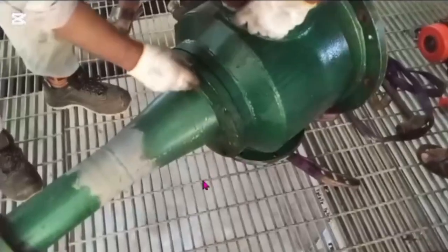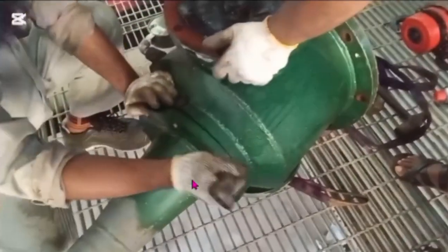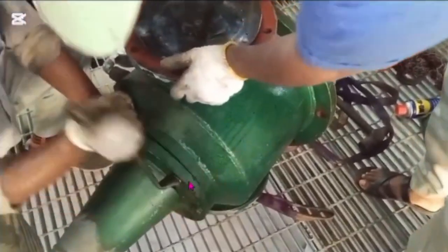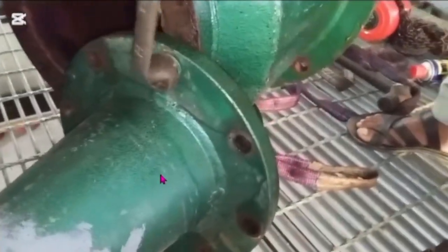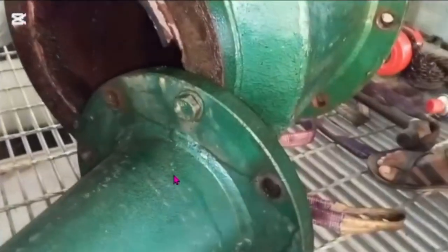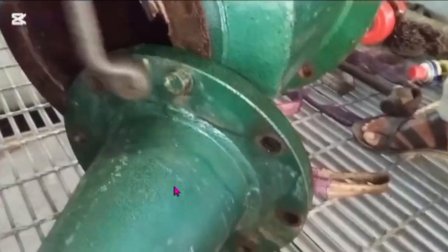Here we saw inside the valve by borescope. Also here is some leakage. Here is a hole. We opened the ejector lower part. This is the lower part, and we changed this part. By the ejector, the appropriate vacuum is made to run the turbine.